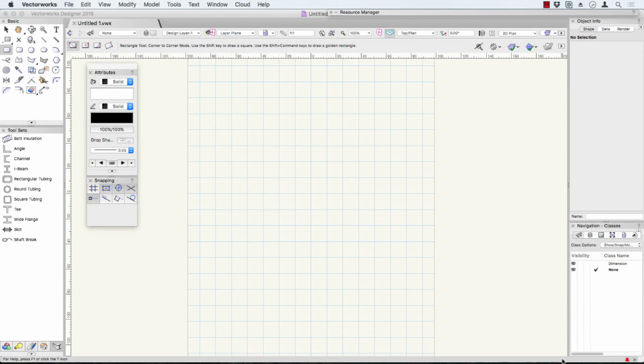I'd like you to keep your eye on this area just down the bottom here. Just here where my cursor is. As I move around, or I draw a line, you sometimes notice that there's an X, Y, length and angle available. That will also appear as a floating data bar when I draw something. If I make a mistake, you might notice this area down the bottom here presents you with a red error message. So that can be quite handy if you keep your eye on that.